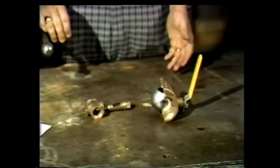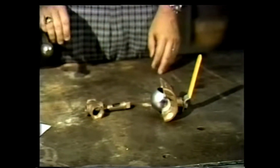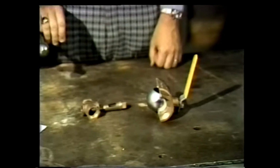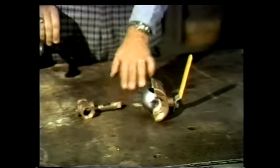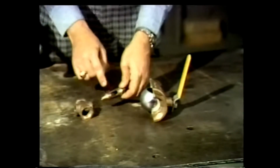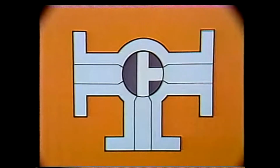Usually this design does not provide the same tight sealing quality of the globe valve, but these valves aren't generally used in systems requiring a tight shutoff. Often you'll see plug and ball valves on lubricating systems, such as on a duplex strainer. A plug or ball valve can be single port, or it can be multi-port valve.